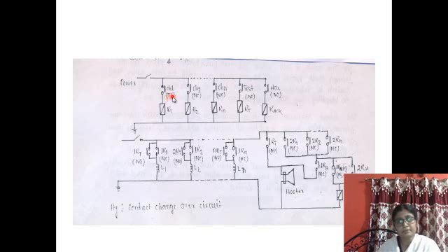Now what will happen? Just check. This is normally closed type. If the channel is in healthy condition, that means the particular relay for that channel is in de-energized state, so this contact is in closed position.